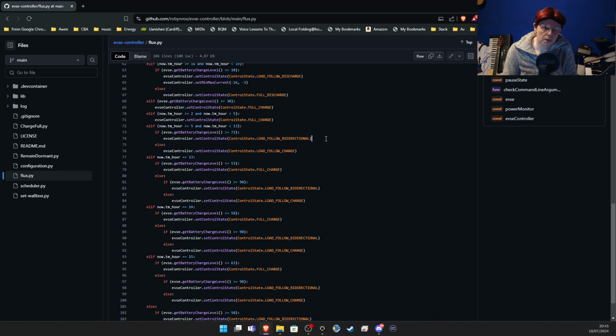And also, I can't use all of the energy from my solar panels. If the state of charge has got to 97%, and the clouds come over and I want to run the kettle, that would be a good time for the Wallbox to start sending some power into the home to power that, because it's cheaper than getting energy from the grid at that point.